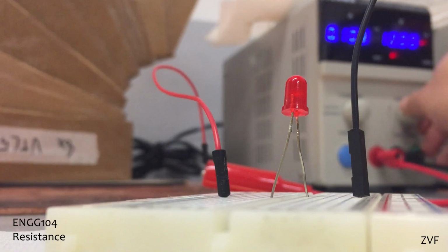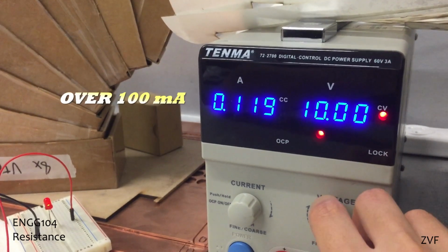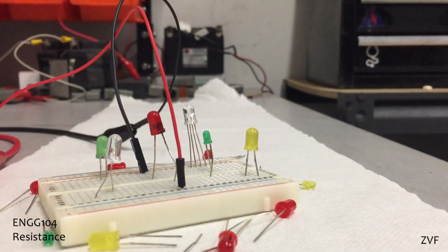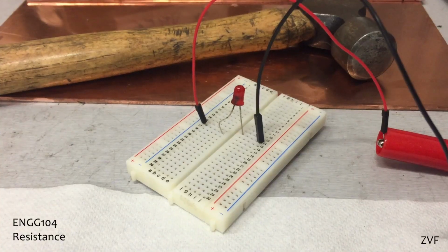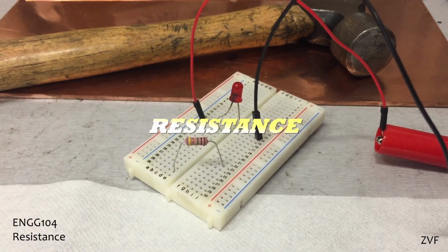Consider an LED, subjected to a supply of 15 volts, but designed for about 2 volts and only 30 milliamps of current. LEDs are a common light source, and for such a purpose they must be reliable. As with all electrical components, however, they must be treated with care. To simply manipulate the voltage and current responses throughout this basic LED circuit, controlled resistances can be introduced.